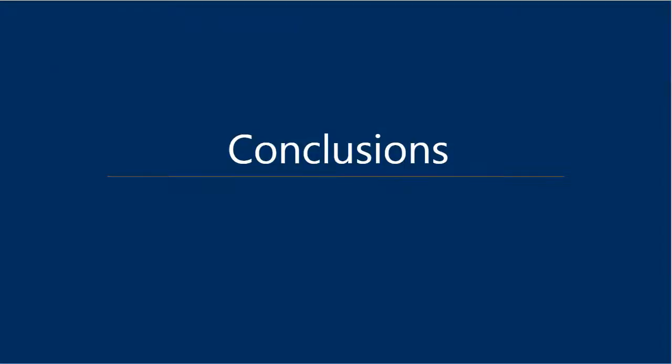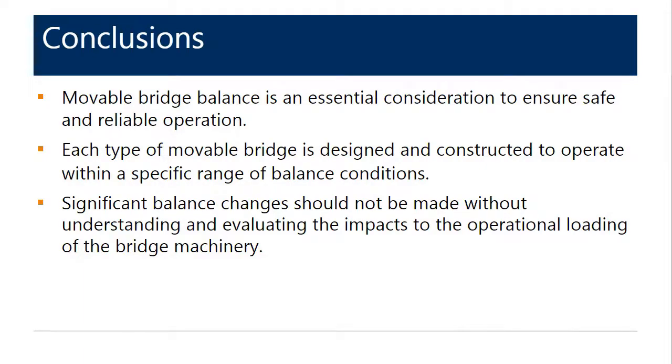So we're almost at the finish line. In conclusion, movable bridge balance is an essential consideration to ensure safe and reliable operation. Each type of movable bridge is designed and constructed to operate with a specific range of imbalance conditions. Significant balance changes should not be made without understanding and evaluating the impacts to the operational loading of the bridge machinery.